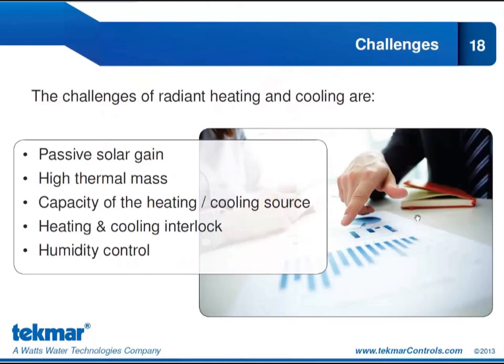And we have to be very mindful of that humidity when we're talking about radiant cooling, because we always make sure that there is no chance of condensation. And so that comes down to the sophisticated control algorithms that are in place to take into account what the relative humidity measurement is and then adjust the water temperatures accordingly.